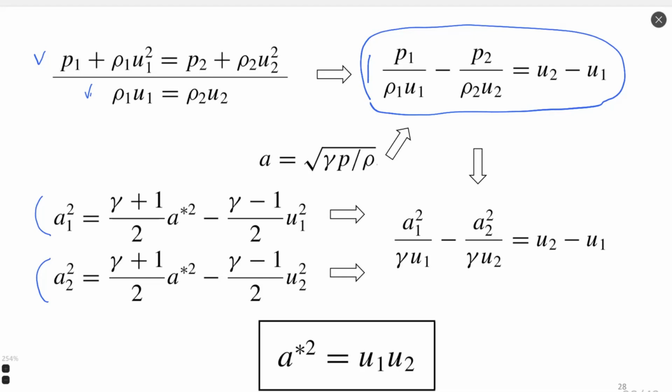For example, in this model, we use a relation between the characteristic speed of sound, at which the Mach number is equal to 1, and the velocity and speed of sound at any arbitrary point. Point 1 is the point before the shock wave, and point 2 is the point after the normal shock wave.